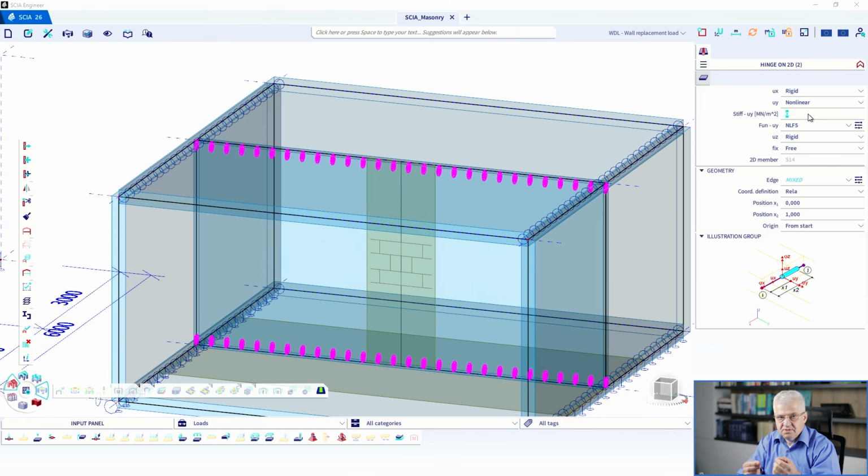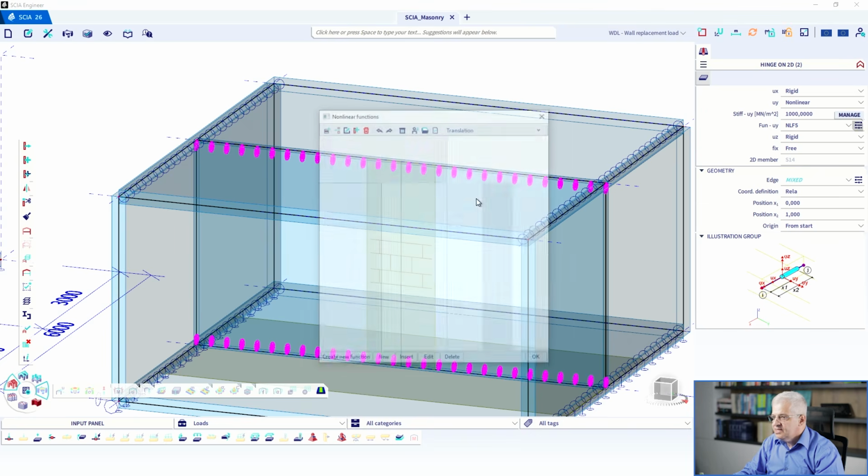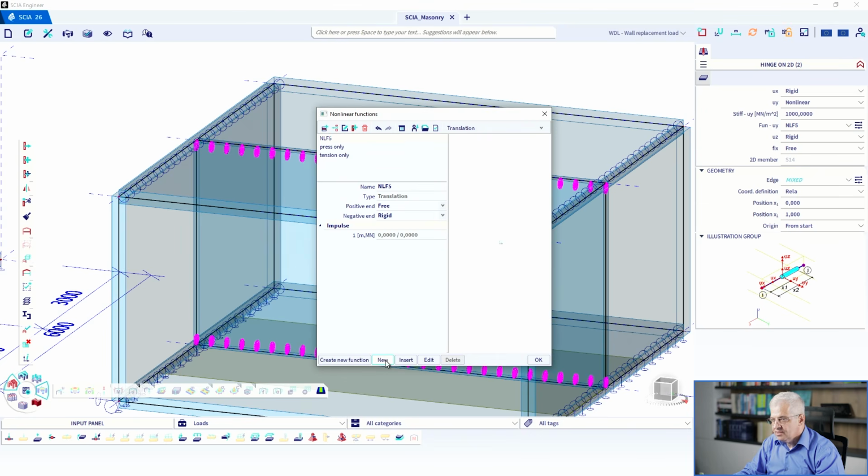I hope it's understandable. Usually I select some higher stiffness because in the worst case, it simply doesn't move. It's better it's not moved, as otherwise you get higher deformation in the first iteration, and then the engineer needs to go back with the deformations on our line. So better you start with higher stiffness. And we need some stiffness. I create a new one.